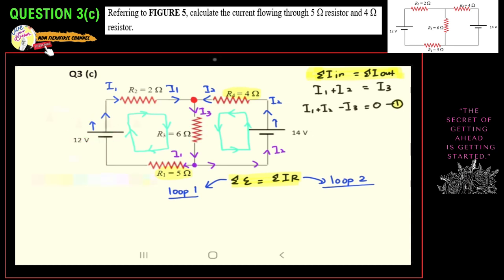Okay, and remember, this small arrow, tengok, comparekan arrow yang kita lukis tadi. Remember, kalau saya dapat soalan Kirchhoff, saya akan lukis small arrow, okay, dekat atas positif tu. Maknanya kita tahu current daripada battery mesti flow through the positive terminal, right? So if the small arrow yang kita lukis atas ini same direction with the loop, so means that the value of the EMF here should be positive. So total EMF for the first loop ada satu saja EMF, so 12. Okay, dia bukan negative 12.